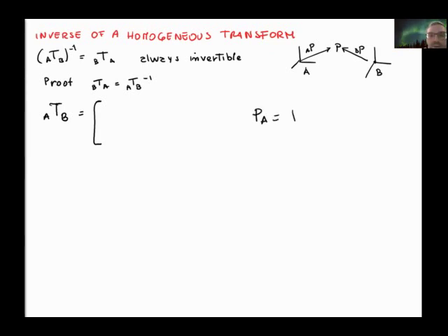This is a point on the A frame. This is the point on the B frame. We need to rotate it from the B to the A frame plus sum the vector that is between the origins of the 2 frames expressed in the A frame.